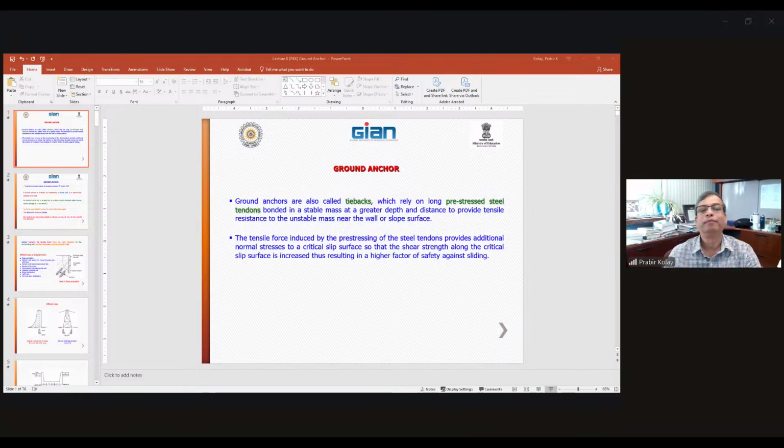So it can be used for deep excavation. It can be used for vertical rock anchors for tying a concrete dam with its base, anchors in tall installation towers, anchors in dry rock, conventional concrete gravity dams, highway retaining walls, and slope stabilization. There are several applications. The idea is that the anchor transmits the tensile force from the main structure to the surrounding soil. Over here is the anchor, and some portion of it is filled with grout. We'll talk more about that.